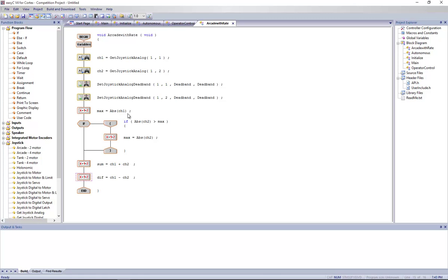Note that all of this coding that I'm going to do is valid when forwards means that both motors run at positive full throttle, backwards at negative full throttle, and that the left motor is really plugged in the left motor and the right motor is really plugged in the right motor. I strongly suggest that you check your wiring, your electricity, in order to see if it's really the case. If not, well, the function will not work. Then you'll have to check what motor is at fault. If you have to switch between the two motors or switch the polarities of the motors, that's up to you. But you'll eventually get it. All right, so let's do some more complex stuff.